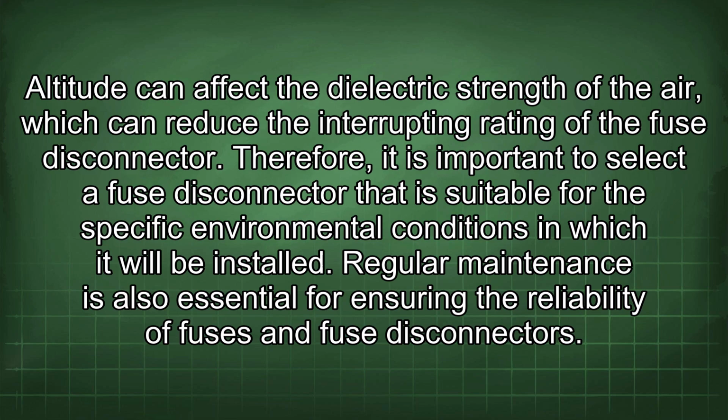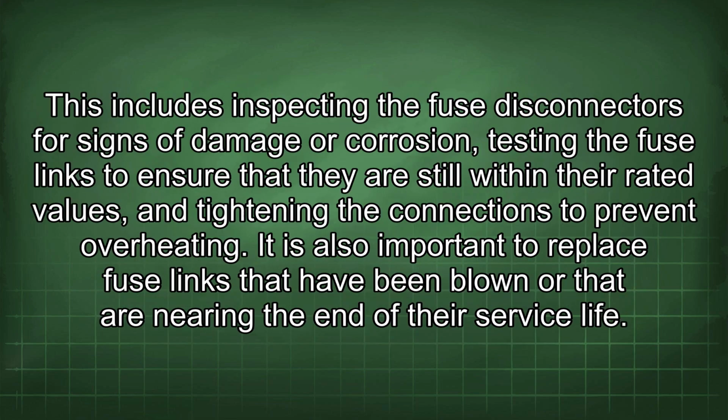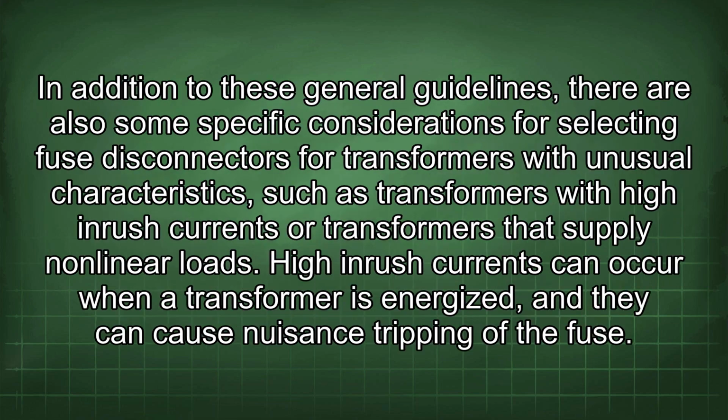Regular maintenance is also essential for ensuring the reliability of fuses and fuse disconnectors. This includes inspecting the fuse disconnectors for signs of damage or corrosion, testing the fuse links to ensure that they are still within the rated values, and tightening the connections to prevent overheating. It is also important to replace fuse links that have been blown or that are nearing the end of their service life.